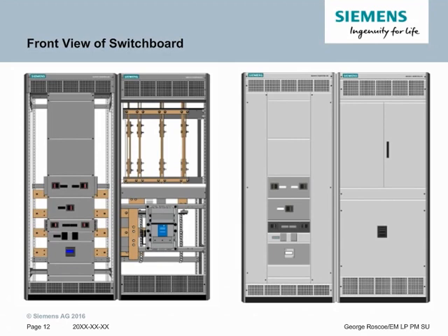Here's an example of a typical distribution switchboard. The incoming is in the section on the right with the utility metering section on top. The key giveaway there is that the busing is mounted through, spaced out, and would allow for CTs and PTs to be placed on it. The other giveaway that's the main section is that they have an individually mounted main breaker. That is very common, and most of our breakers are individually mounted mains.